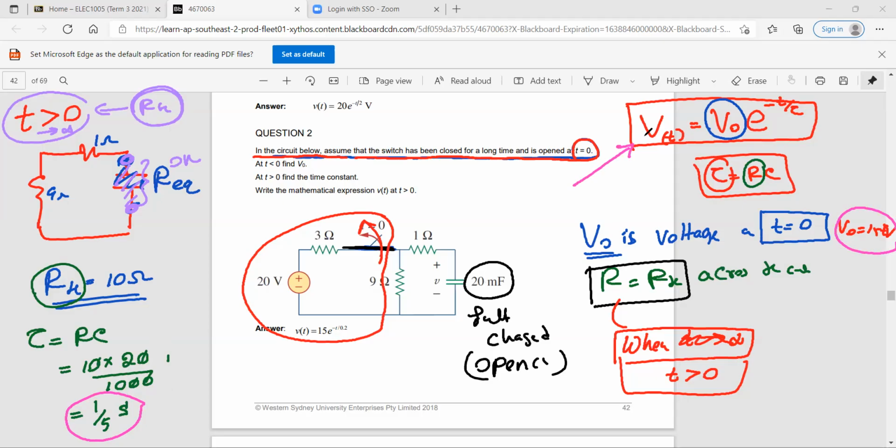So you just substitute in this equation. When you substitute the things in the equation, you have Vt is equals to 15 times e to the power minus 5t. Am I right? So this is what they're asking you to find. So this is how the voltage changes across the capacitor. For any given t, if someone gives you the t, you can find the corresponding V for that t because you just substitute that t over here. Does it make sense, guys? Any question?